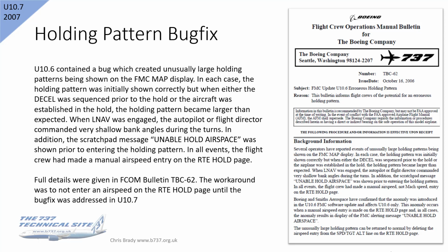Another bug fix which was addressed was for holding patterns. The FMC would, under certain circumstances, create unusually large holding patterns. Initially it was shown correct, but when either a deceleration was sequenced or the aircraft was established in the hold, it suddenly jumped and became larger than expected.